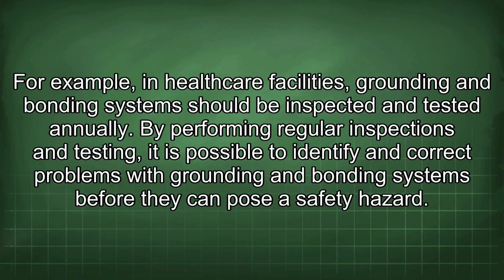For example, in healthcare facilities, grounding and bonding systems should be inspected and tested annually. By performing regular inspections and testing, it is possible to identify and correct problems with grounding and bonding systems before they can pose a safety hazard.